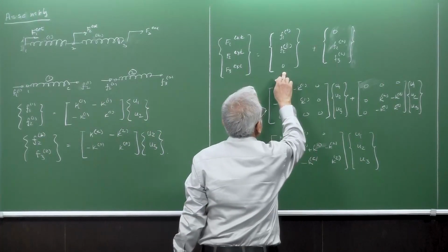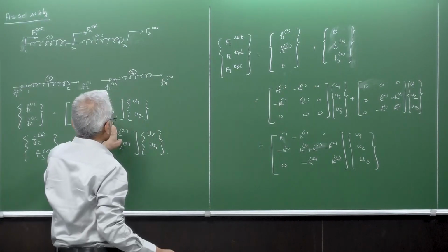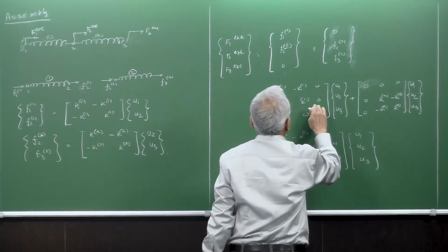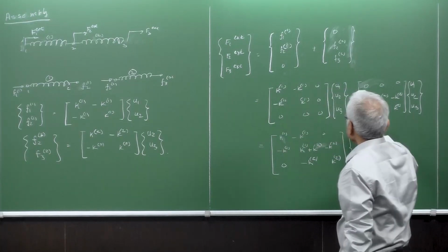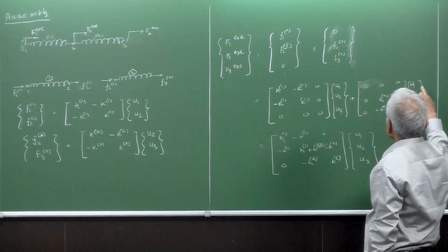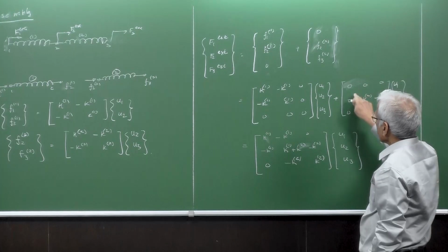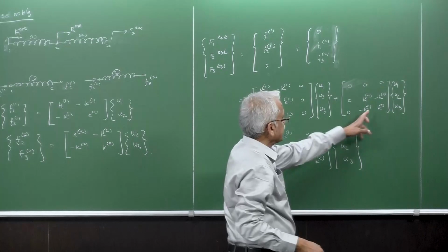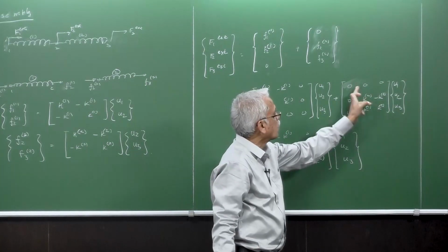This one can be obtained from this one by adding an extra third row and a third column here. So you can very well see that this is equal to this one. Similarly, this one, a contribution from element 2, can be seen coming from U1, U2, U3, and the top row and the first column are zeros because this element will not be contributing anything to node 1.